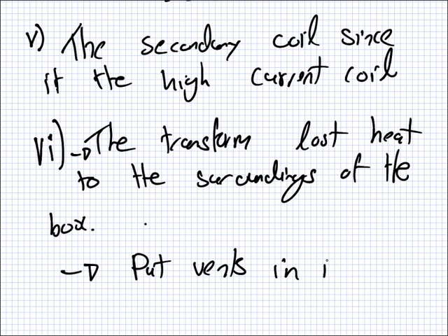I don't know what the marking scheme says. Changing flux linkage through aluminum casing due to magnetic field from transformer. That's 1 mark. Was the question why does the transformer get hot or why does the box get hot? No, it's just a reason for this heating effect and a way to reduce it. So technically it's why and how to do it. Why it happens and then how to reduce it. What did it say for how to reduce it? Remove casing. Yeah, it's a sensible method of reduction. For example, change material of casing or remove it, or reduce leakage of flux from the core.